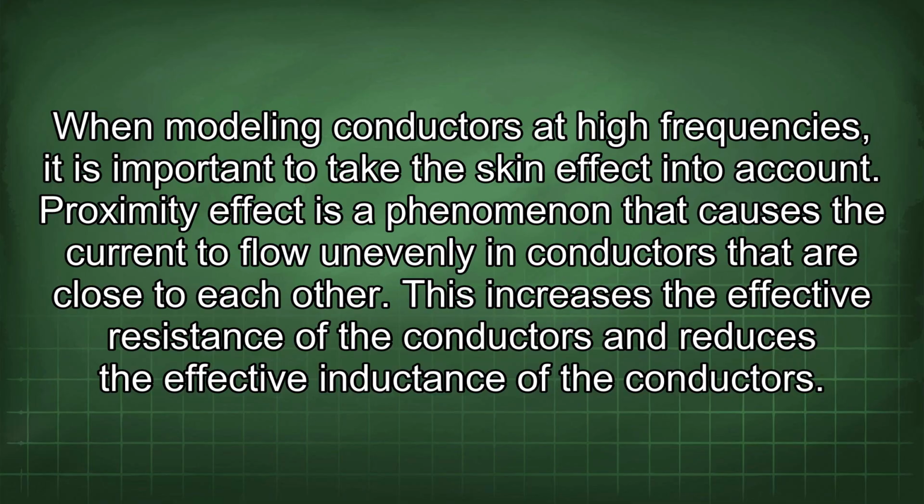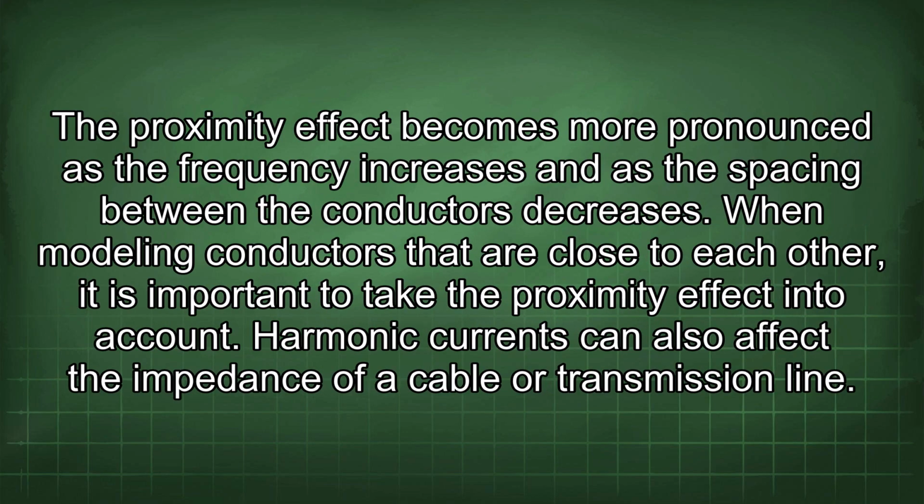Proximity effect is a phenomenon that causes the current to flow unevenly in conductors that are close to each other. This increases the effective resistance of the conductors and reduces the effective inductance of the conductors. The proximity effect becomes more pronounced as the frequency increases and as the spacing between the conductors decreases. When modeling conductors that are close to each other, it is important to take the proximity effect into account.